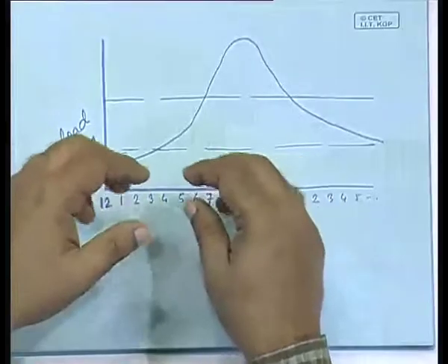Also, if you have hydroelectric power, it after all comes from the rain, and the rain is varying all the time. So if you have a rainy season, you have a huge amount of water available, and the same water can be used to cater to the base load, because it is there anyway, we have it. So the majority of the power production can be shifted to hydroelectric in those periods, and during the lean periods you may use it only for the peaking purpose.